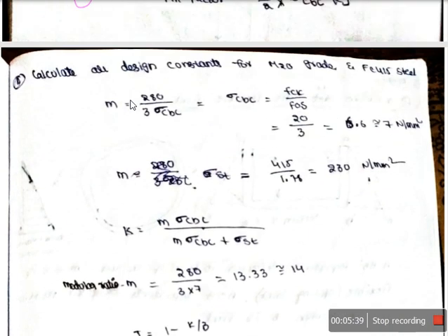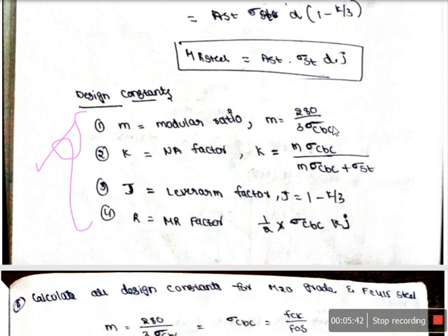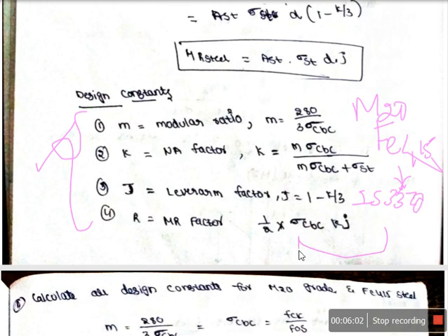So for a small example problem, you can take any sigma_c, any grade of concrete and any grade of steel, and based upon this refer to IS 3370, and then you can calculate all these four values, because these four values give you the very basic and important inputs if you want to follow working stress design.